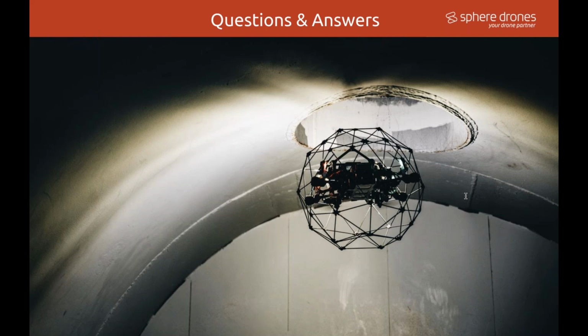And then the FCC ring that I showed you, the one with the hexagonal meshes and refractory, was a 60 centimeter diameter tube. So you could get your camera right onto the concrete. I think it's accurate to say that's a 1 millimeter accuracy model, because it's so tiny. You have very short distances between the camera and the thing you're filming, so that gives you a high GSD, and that gives you a high accuracy as well.